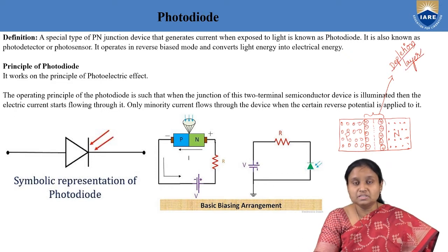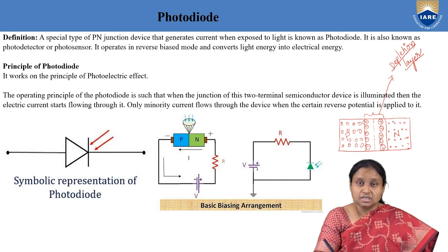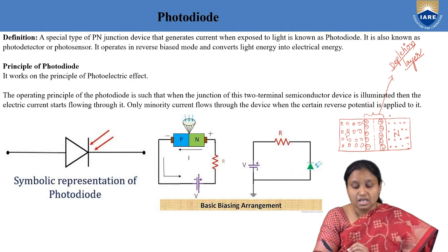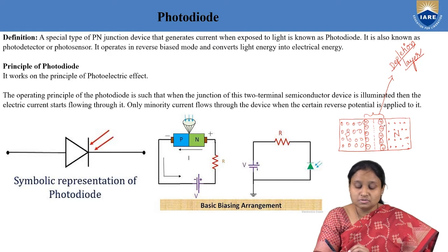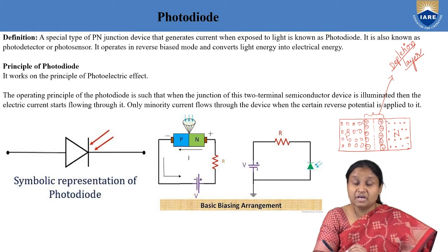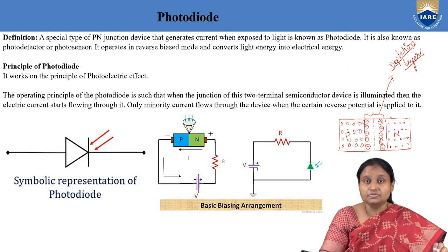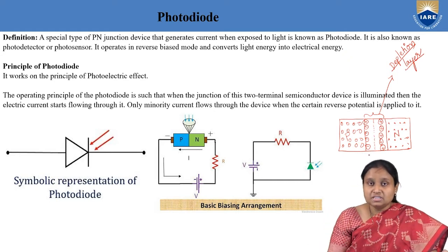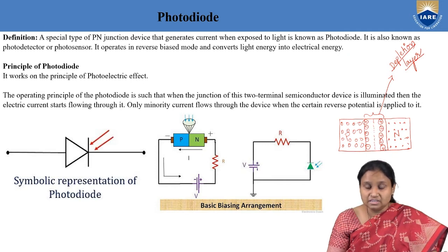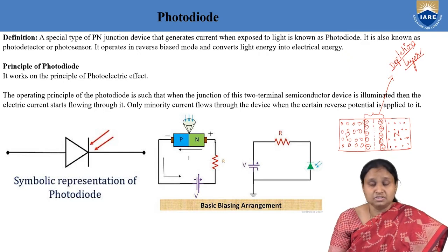And why is it called the depletion layer? Because in this layer we are depleted of charge carriers. There are no mobile charge carriers, all of them are immobile ions without any energy. Of course, a voltage is also developed. That voltage is called the barrier voltage, or simply the potential barrier, which prevents further diffusion of charge carriers. So once the PN junction is formed, there is a formation of a junction or depletion layer in between the P-type and N-type semiconductors.